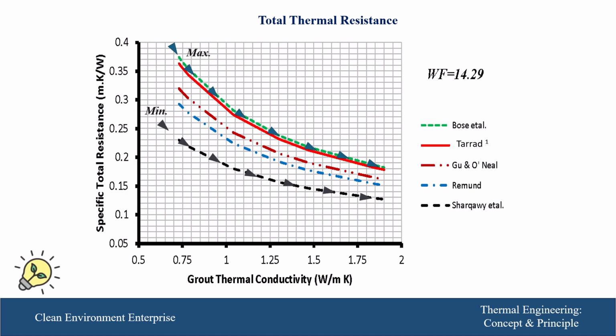And these values dictate that attention should be paid before selecting the equation to be used, because this total resistance will reflect the heat loading of the heat exchanger, and that will give the depth of the heat exchanger.